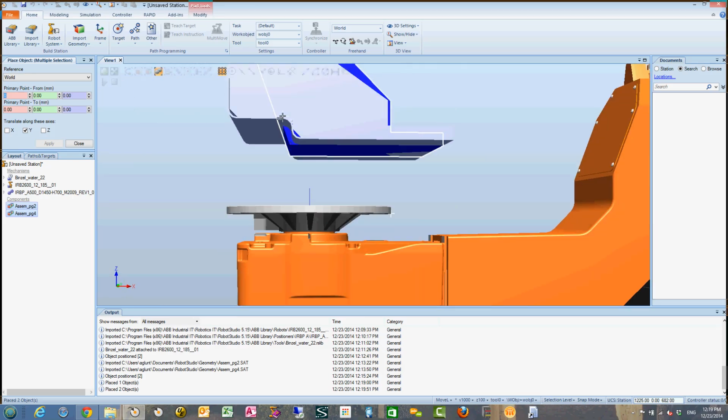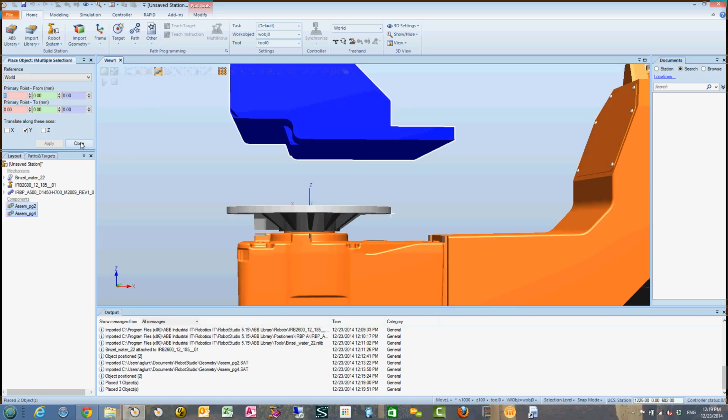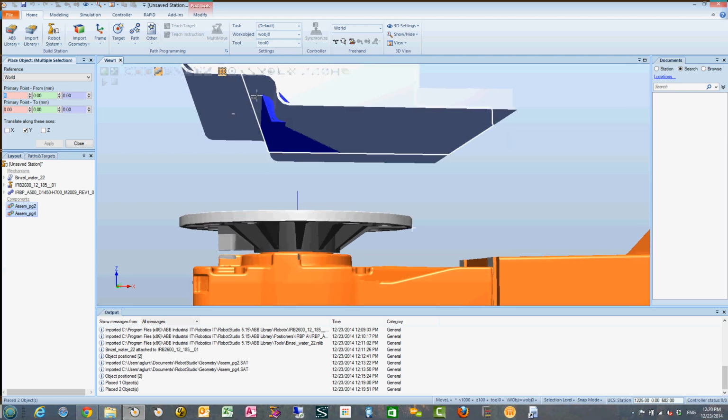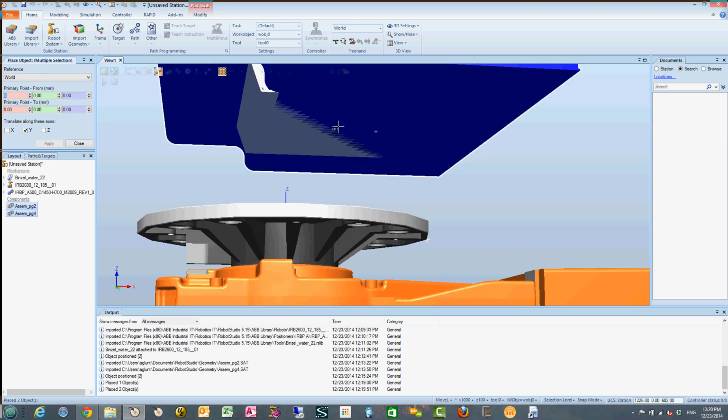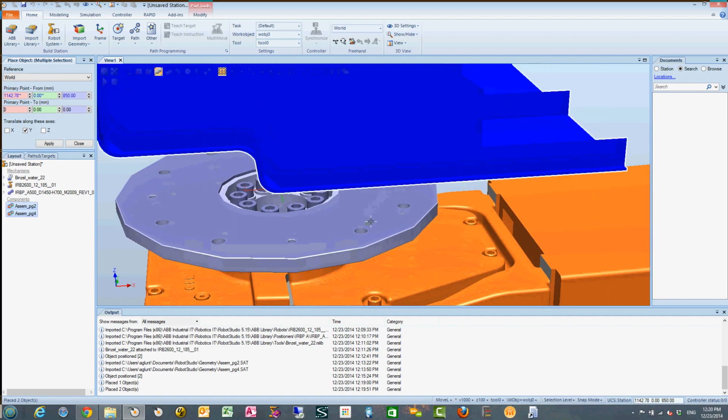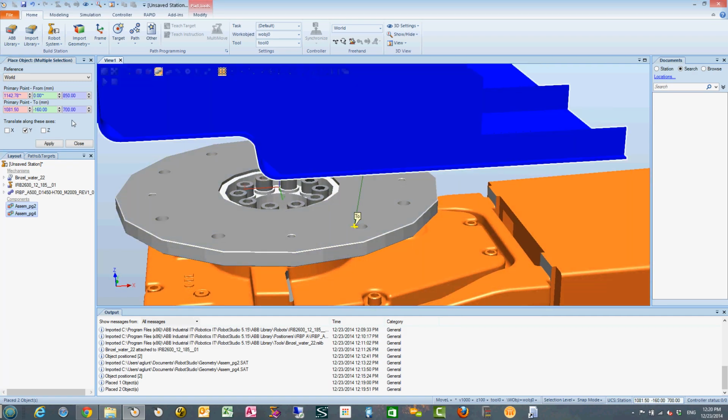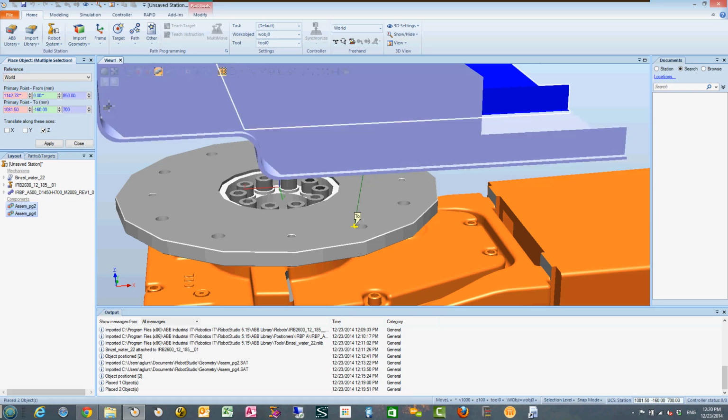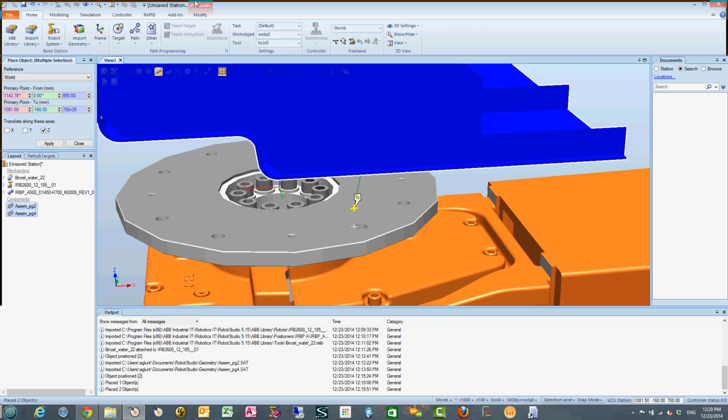And so now I need to move them both down a little bit. I can say, you know what, this is actually too high. So I'm going to go from there to the top of this right here, but only, so that's 850 to 700, so it's 150 millimeters difference, but I only want to move the Z, and I want it to be 25 millimeters off, so I'm going to go plus 25, and then hit apply.